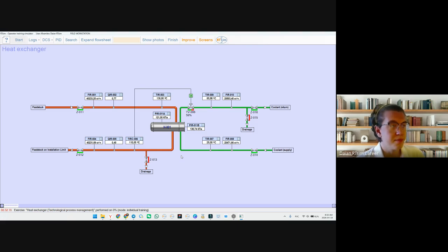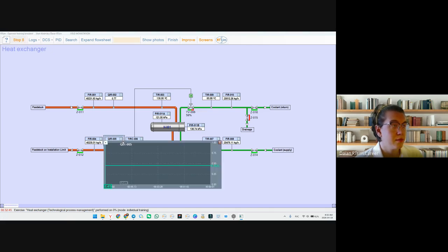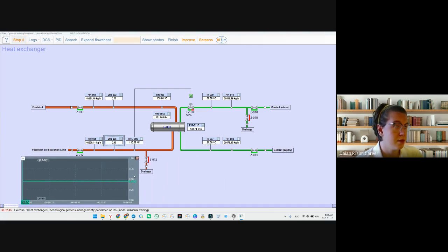Naming rules are the same. Q means quantity. Distillate quantity is a ratio between vapor phase and total quantity. Consequently, 1 is the maximum value of vapor phase in the system, and 0 means that all production is in the liquid phase. Now let's open the trend, but first of all, we should start the calculation. Let's find here T.